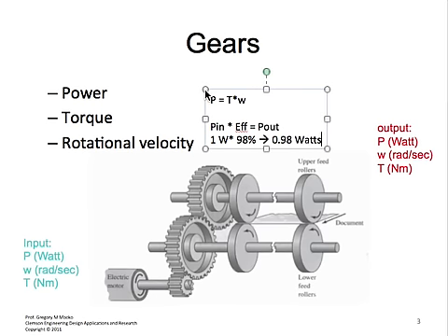And the efficiency is related to the amount of losses within each of the gears. So you can imagine that as we increase the number of gears associated with a spur gear train, our efficiency would go down. Efficiency is also related to the types of gears chosen, the materials that you use, the lubrication that you put on them, and the conditions that they're in. So keep in mind, again, that gears and gear trains are designed to transmit power.